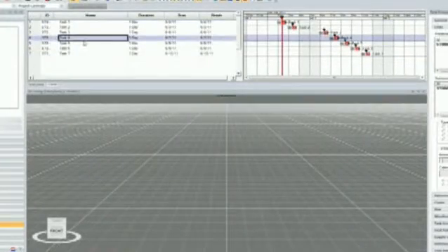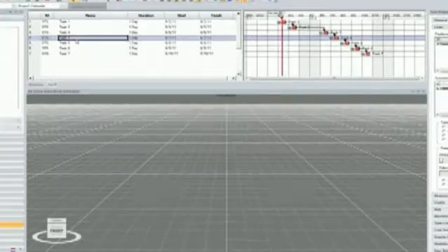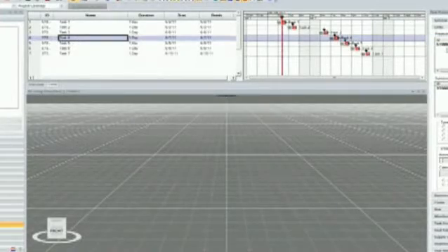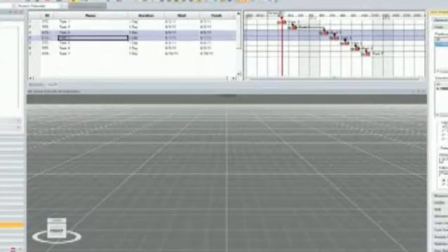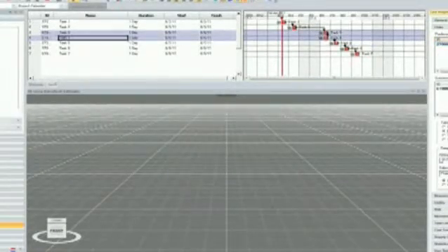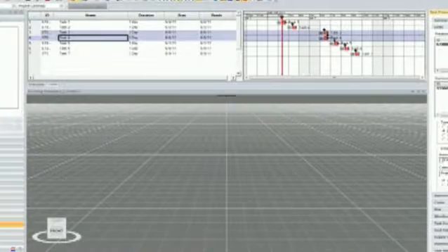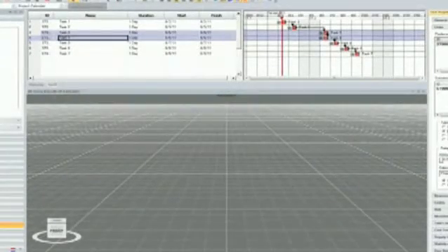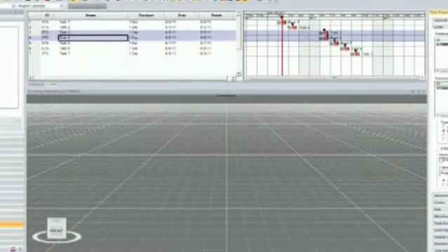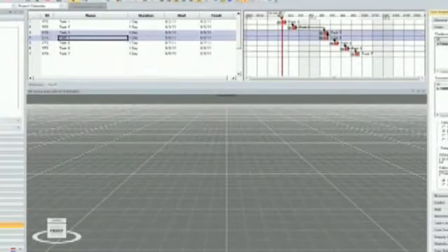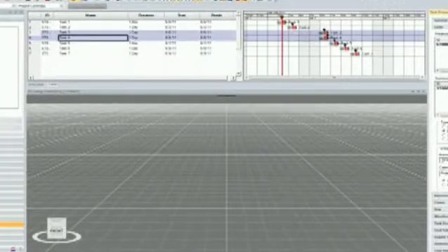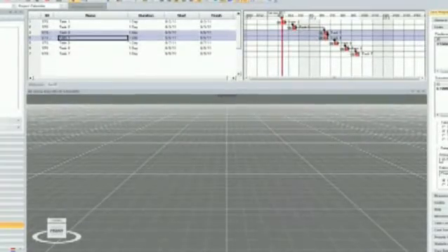Okay, so now if you noticed, I've now created logic, and I'm going to highlight task 4, and in my links now you can see my predecessors and my successors. And if I click on predecessor, it'll show me the logic. Then just start, and if I want to change it, I can just change the logic directly in Synchro. And this is our lag or delay. Most people like to call it lag. We can go positive or negative. So we have the scheduling capabilities in Synchro, and we've worked really hard on the ability to be a really solid scheduling system for construction. So we control the schedule in Synchro.